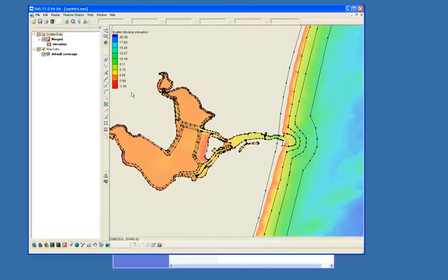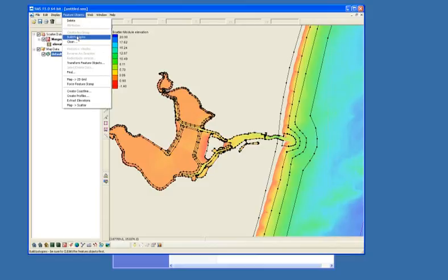And once you have these zones created, that's not really saying how much resolution to put for each one of these zones. So to do that, you would go under Feature Objects in the Map module, Feature Objects, and Build Polygons.